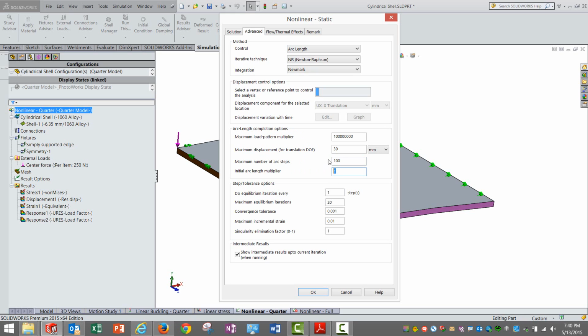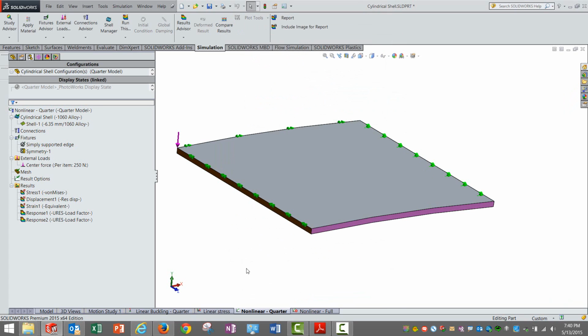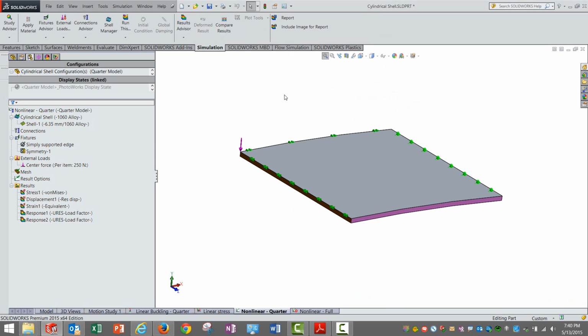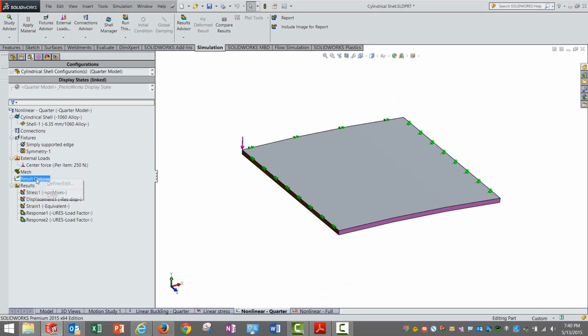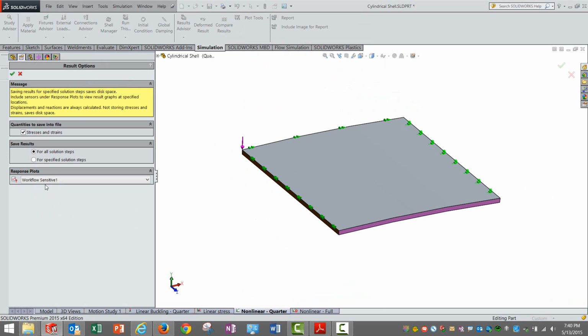Now frankly, it is difficult to come up with these values easily. You can leave them at these values. Maximum displacement can be interpreted. This is typically 1E8, so these two are almost decided, and it's no harm in giving this value on the higher side. Obviously, these two would affect the accuracy, so you may be a bit cautious. But it is difficult to decide these values, in the sense that you cannot start off knowing the exact values initially. We'll discuss a little bit more on this topic.